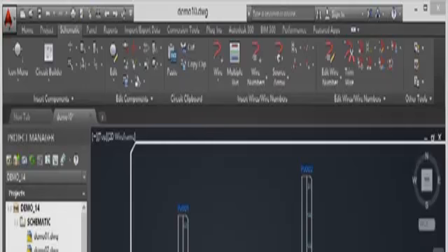Let me just hit enter and take you through that one more time. It's a little bit of a weird concept to grasp. I select the component, I right click and rotate connector. So then I do a right click and hold, and this time I'll say yes, hold attributes at original orientation. So if I say yes to that, you'll notice all of the attributes are horizontal, PJ001 and the 4 pins, 01 through 04. So if I rotate, watch the orientation of the text. It all stays horizontal. If I do it again, horizontal, again, horizontal, again, horizontal, enter to finish.